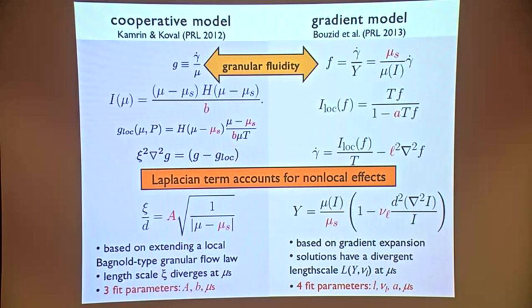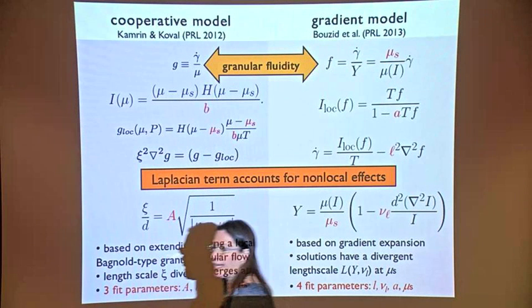You would think, and again, this is the definition of the inertial number, it comes from gamma dot times time, but then that is allowed to have a diffusion of fluidity. If you tried to write the inertial number as a function of μ to better and better precision, you would add Taylor series terms to that, and this is now a gradient expansion, on doing a better job of writing your inertial number.